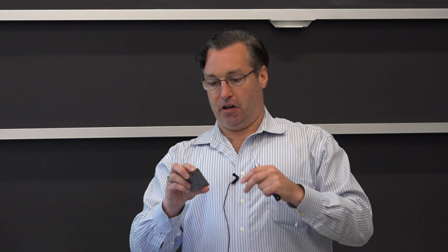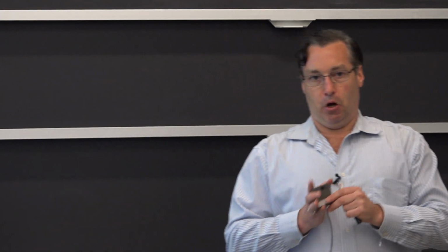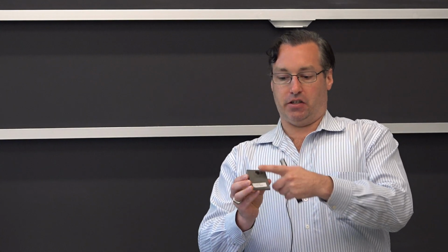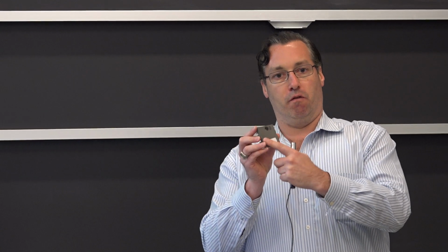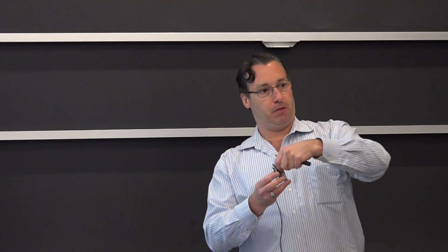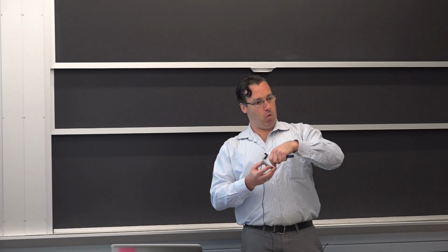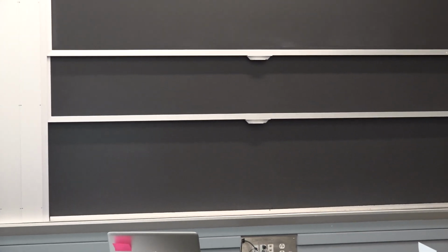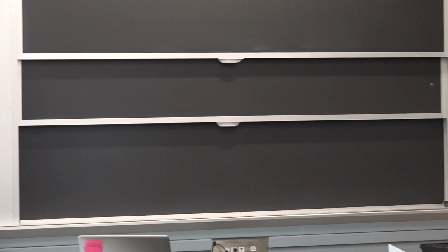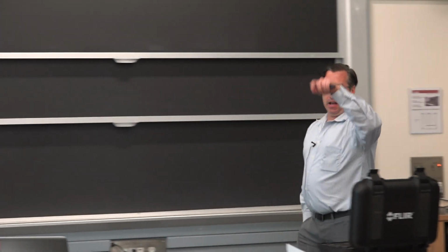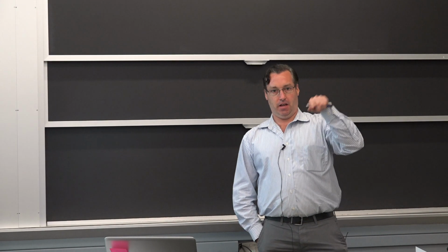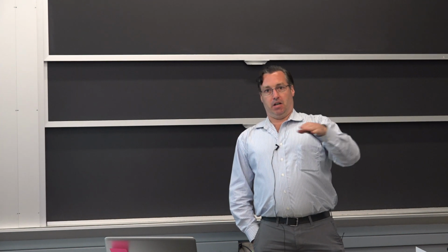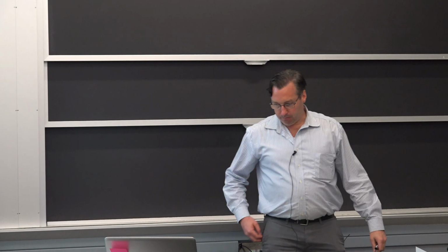As you see here, it has complex geometry of various shapes, but if you look closely, you can actually see the indications, the cracks on the surface here, and you can see there is a bit of a taper as you go over the sample. So this is the issue of liftoff from when I showed you the video when the inspector's going over it with the probe. What shows on the traditional eddy current is the Lissajous signals, the ones that kind of look like butterflies on the XY scan. That is a function of the bit of a saddle to the component.